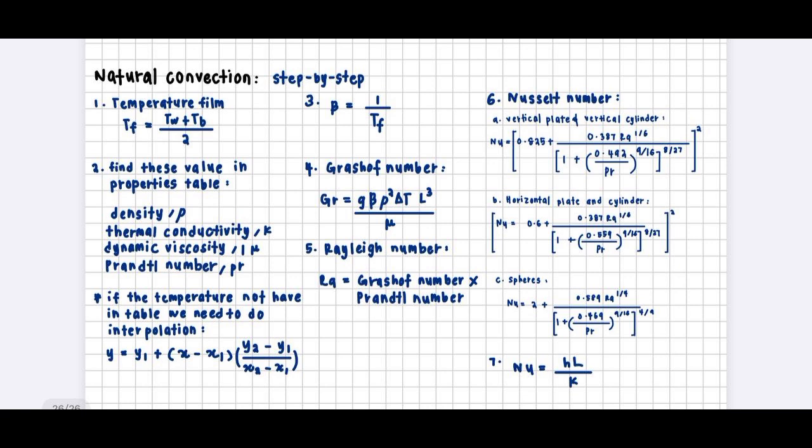Okay, lastly, you need to calculate the heat transfer coefficient. From the equation, you need to solve for h. So you need to move the h to the other side. Then we will get the equation h equals Nu times k divided by L.